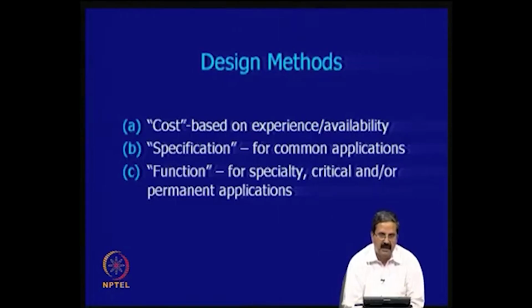And also the availability: depending on the availability of a material, you design for whatever work can be done. Based on experience, if you see that a particular geotextile has been useful in one application, and you have a similar application elsewhere, you can do that. That is what people do. We say that, yeah, it worked there, so it will work here.